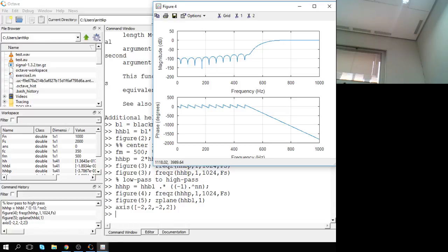And then you have the control on high frequencies, maybe a little bit higher also on that one. The mid-range control basically is the volume control. So you have 3 bands. On a digital filter: from 0 to 200 hertz, from 200 to 2 kilohertz, from 2 kilohertz to, well, the Nyquist rate.